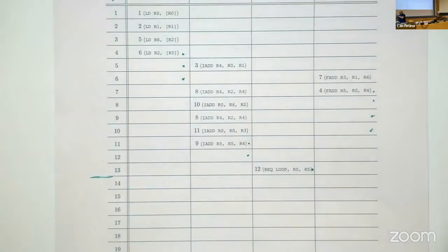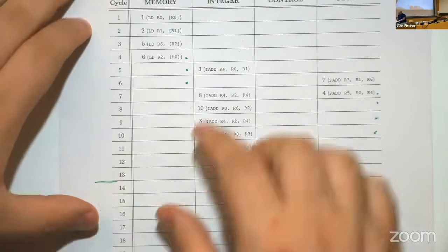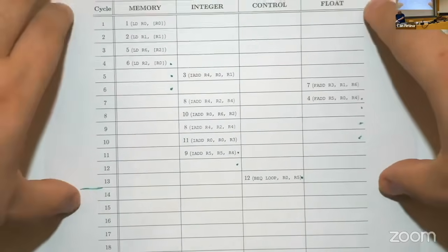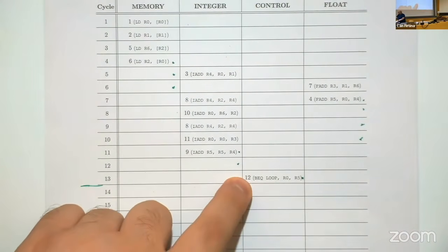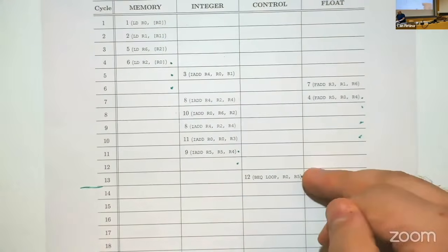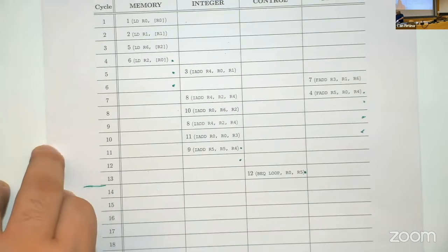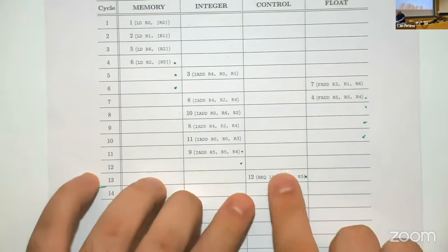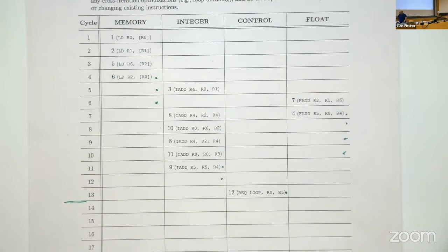So be careful with this, start from 0 and the number of cycles. This is always very tricky, right? But we take up the entirety of 13 cycles to be done, and this one takes 1 cycle to execute, right? This branch on equals. So it is actually done by the 13th cycle. So that's why we use that in the denominator. If, for example, this had a latency of 2, then you're right. You would have had to use 14 instead of 13. Okay, does that make sense? Okay, cool. Anything else?